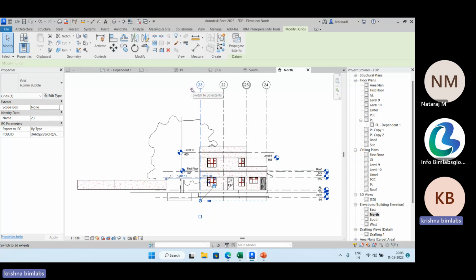So that is datum elements and scope box. Scope box is just for splitting the plan and placing it in the sheet. Datum elements means managing datum elements. To manage the datum elements or make them view specific, you can just convert them to 2D and manage specifications and all.